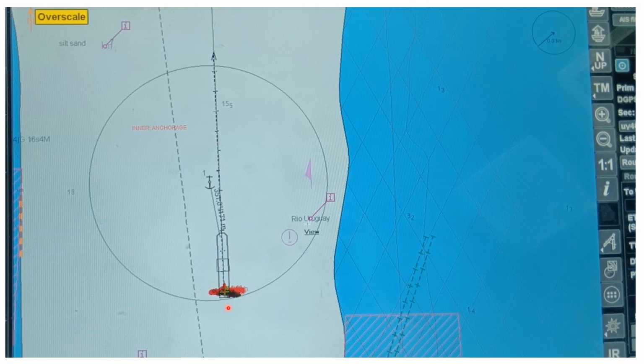So in case you put allowance, even if your anchor is already dragging by 10 meters, but you put allowance in the swinging circle of about 50, it will not produce alarm yet because you have allowance of another 50 meters out, expanding here. So that's the difference of not putting allowance and adding allowance of about 50 to 100.